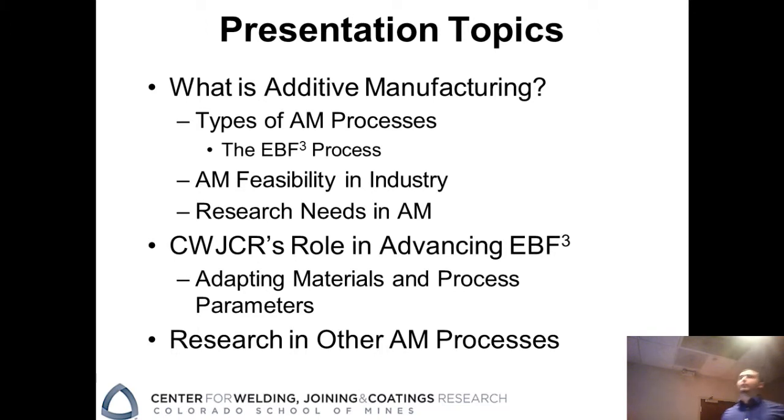This one is really heavy in the aerospace industry, and it's for a lot of large-scale parts. So this would be the type of process that would be more related towards some more structural applications rather than the powder bed processes that a lot of people see from the small 3D printers. I'm going to talk a little bit about the feasibility of industry, how industry could implement additive manufacturing, and the research needs that still need to go into this to push it forward as a valid type of manufacturing process. And then I'm going to talk about our role in how we've tried to advance the EBF3 process.